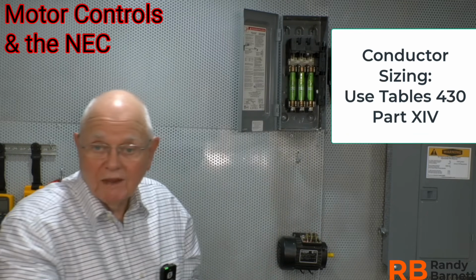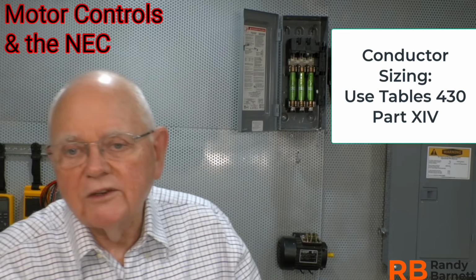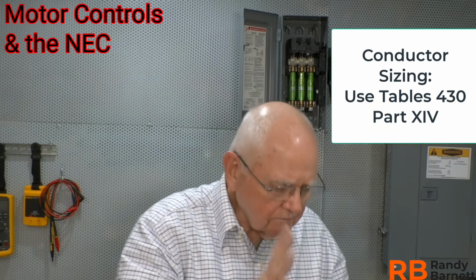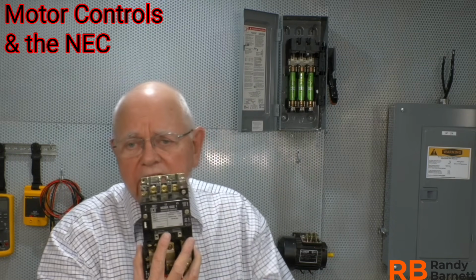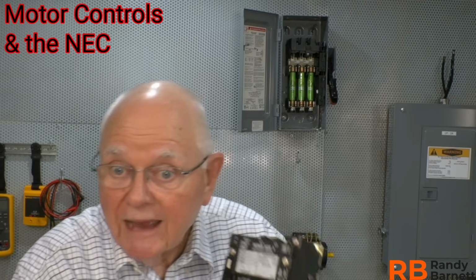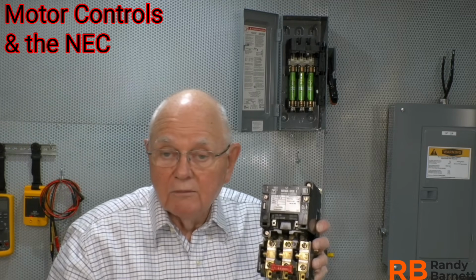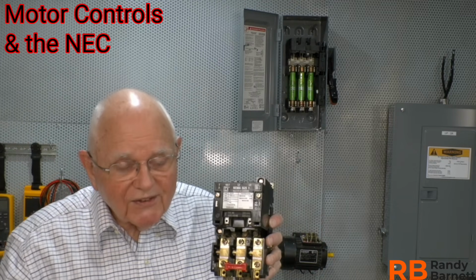Then, of course, I have to make my adjustment and correction factors and account for voltage drop if need be, and all of those type things. Now, let's talk a little bit about the control of this particular relay. I can manually operate this, and this is not a good thing to do. This is not safe. But maybe you've seen people do this out in the field.